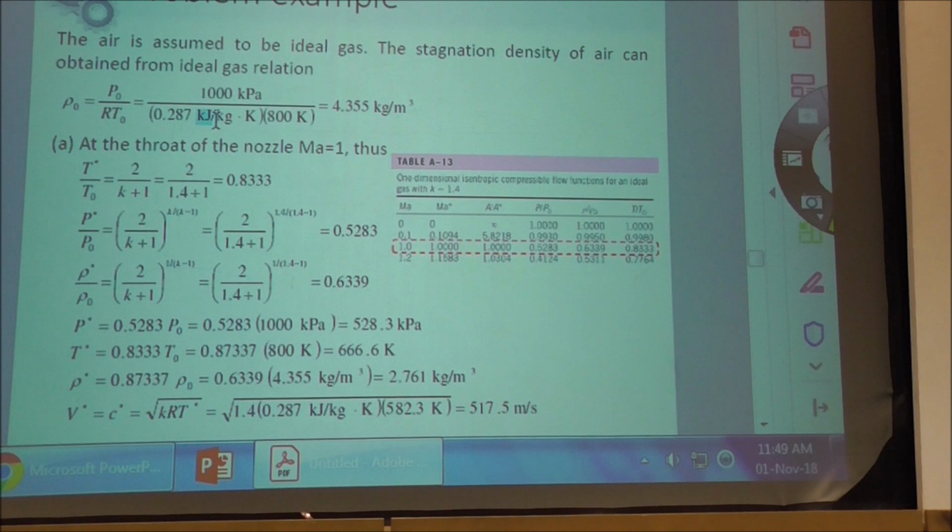As I told you, if you get k equal to 1.4 and your Mach number is exactly the same as those in the table, let's say you get air with Mach 2.4, then you can use the table. But if you are having air but the Mach number is 2.68, you cannot use the table anymore, because interpolation will not give you a good result. Remember that. Interpolation will not do well in this case, because your interpolation is linear while the calculation is not linear at all.